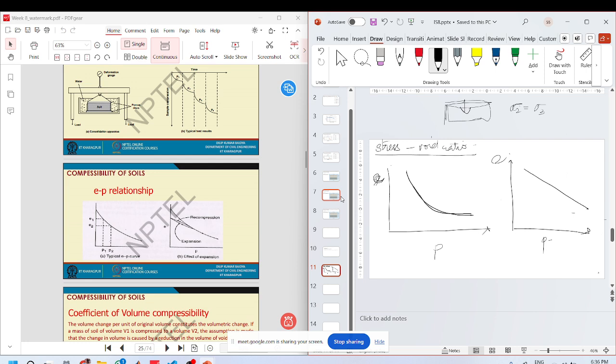And if we talk about pre-consolidation, over-consolidated and normally consolidated soils, we mentioned yesterday when we were talking about NC and OC soils. OC soil is something that, for example, let me say that this is a soil sample. I have loaded it up till 100 kPa, and initially it was something like this. Then I loaded it and it got compressed.